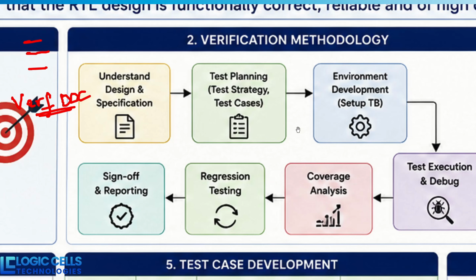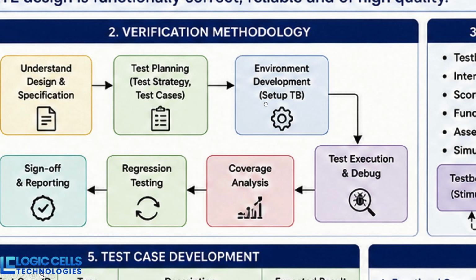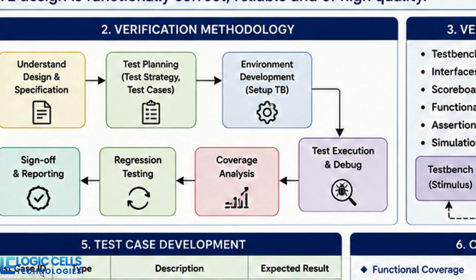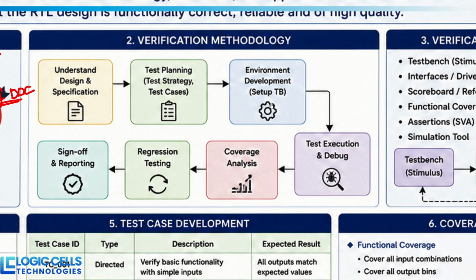Then environment development means the exact test bench. I showed you yesterday the SystemVerilog test bench that has multiple classes, right? That class-based test environment will be developed once we decide on our test plan, the strategy, and the test cases I am going to achieve.